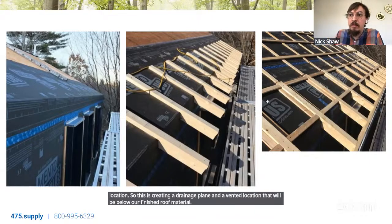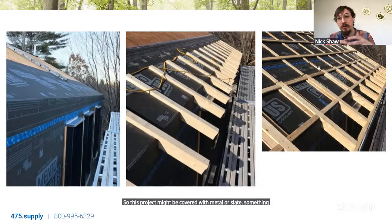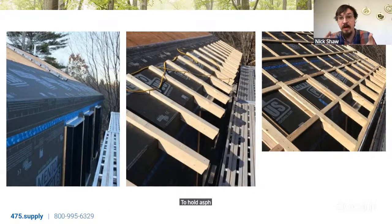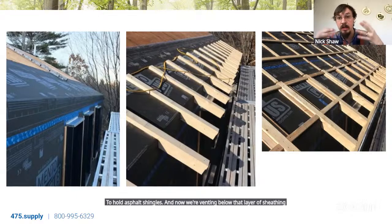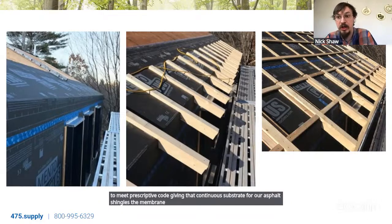So this project might be covered with metal or slate, something like that. But most oftentimes we're actually seeing an additional layer of sheathing to hold asphalt shingles. And now we're venting below that layer of sheathing to meet prescriptive code, giving that continuous substrate for our asphalt shingles. The membrane above that additional layer of sheathing doesn't really matter. It's fine for that to be vapor closed because we're properly venting all below it.